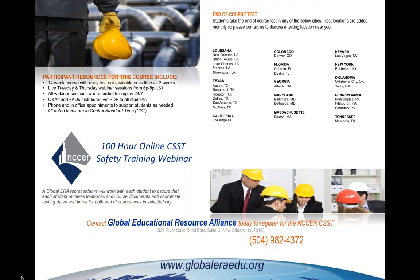Okay, or smoke. Also, respirators may be needed. If they're needed, we need to make sure that employee has been medically evaluated, pulmonary tested, and then ultimately fit tested every year. That fit test is going to be every year. And additional precautions as necessary, depending on the type of equipment that we're using and depending on the metals that we're burning on. Could there possibly be any metals that are galvanized, or any type of epoxy paints? Perfect example are sealers. Okay, and then hot work permits, we have to obtain them. We have to go and clean, and get them up and ready, especially if there's any risk of welding or doing any hot work around a flammable.